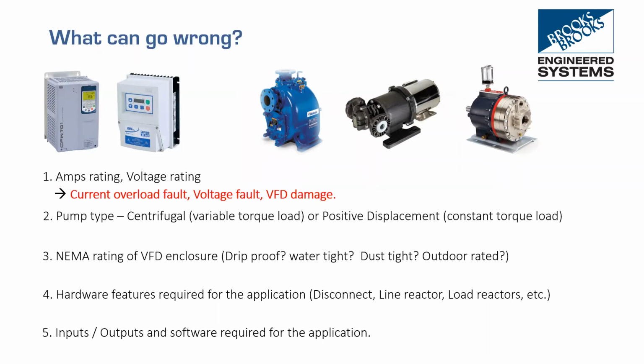The basic selection parameters for a VFD are the current of the motor and the voltage of the motor. A lot of people do preliminary sizing on horsepower, but when you're actually selecting the VFD, you should look at the current rating of the VFD and also make sure that your voltage matches the actual operating voltage of your motor.